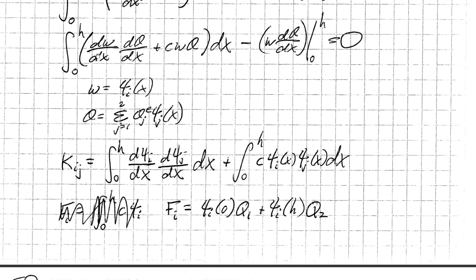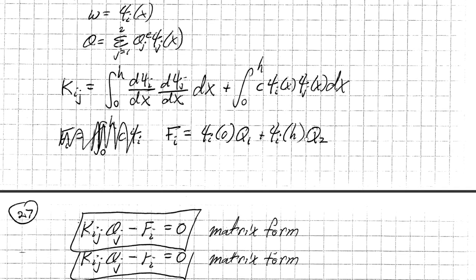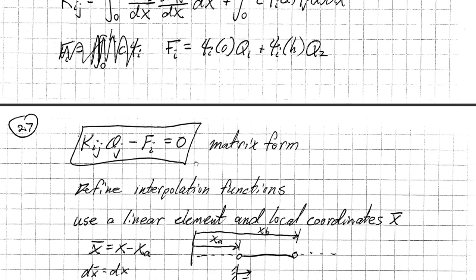For this ODE, when you substitute in these relations, you will get a matrix here, and you also have this term for the convection relation. The terms that are left over get lumped into the flux, so you have your weight function or interpolation function, and you have flux Q1, Q2. So this is your matrix form.